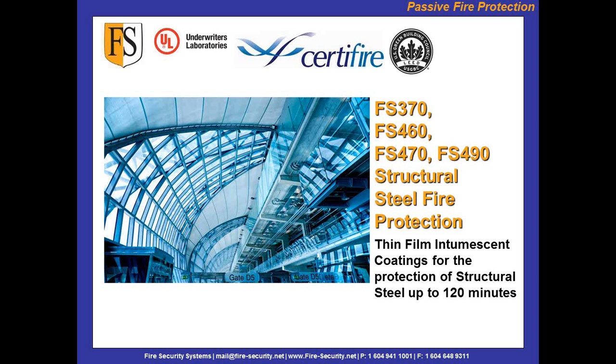That steel section could be attacked by fire on all four sides. If it's a column, for instance, or a non-load bearing beam, it could still be four sides. Or it could be three-sided because it's got a slab on top of it. So you're only protecting three sides of the beam, or even two sides if it's against a wall and a slab. So there are varying degrees of what your HP over A will actually equate to. And a lot of the time you'll find that even steel manufacturers nowadays publish the HP over A factor on their steel charts.